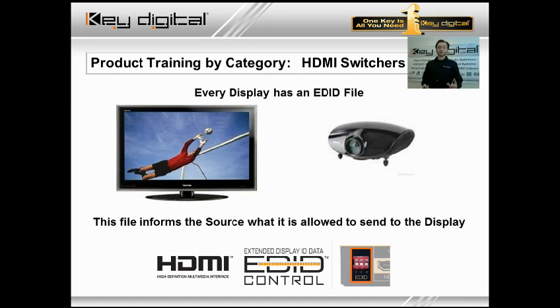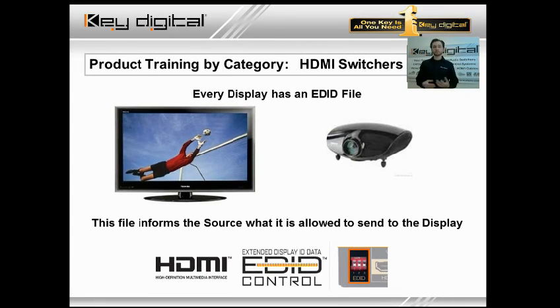presentation. What is EDID? Well, EDID is a part of every HDMI connection. In fact, it actually originated with the VGA connection, the HD15 connection between the monitor and the computer. Essentially what it is, every display has an EDID file. It is a list of preferences, if you will, or compatibilities, if you will, and it is a very important part of the data transmission of an HDMI connection.